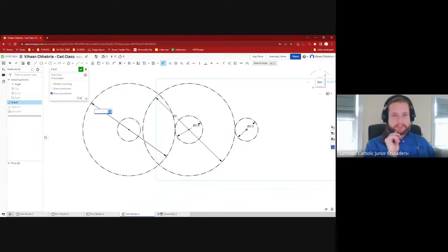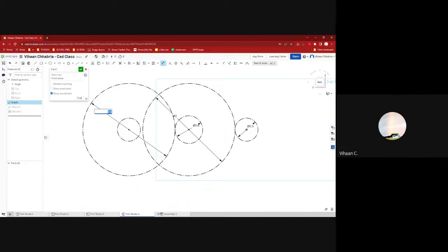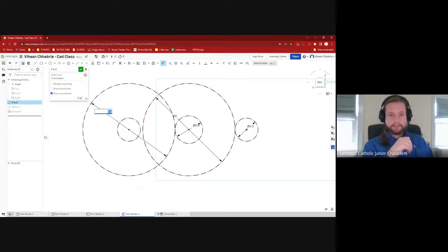And then put a dimension on that of, so it looks like it was 2 inches. And how many teeth would that be? 10. No. Oh, sorry. 40. Yes, good. Good. Did everybody see how Fihan did that? He took the total number of teeth and divided it by 20 and figured out that he needed 40 to get 2 inches.